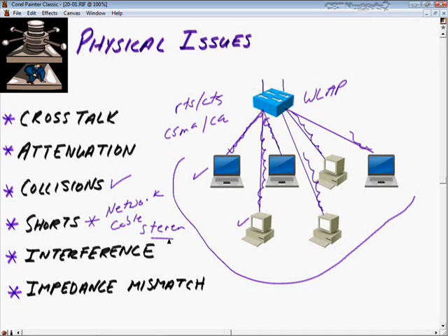And we've already talked about the interference issue. Again, this is going to relate to things like crosstalk. As we know, going from unshielded twisted pair to shielded twisted pair is going to help us with our interference. We know that coax is less susceptible. And then we know, of course, going to fiber optic cable is our best solution for mitigating against interference. You could also change the circumstances. You could try rerunning the cable so it's not going to be susceptible to EMI if it's run next to some machinery or some other mechanical EMI outputs. You could rerun the cable, or you could look at ways to better insulate that cable.